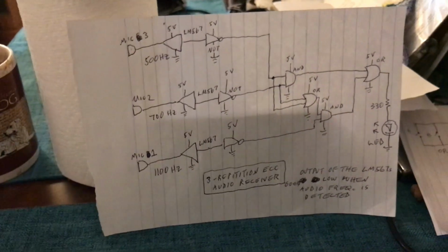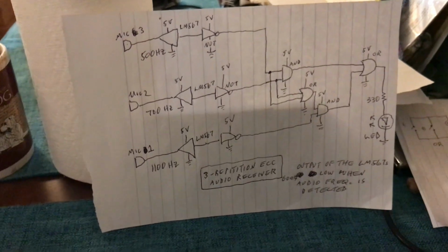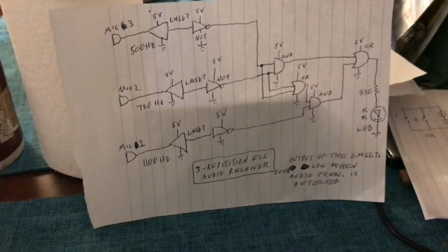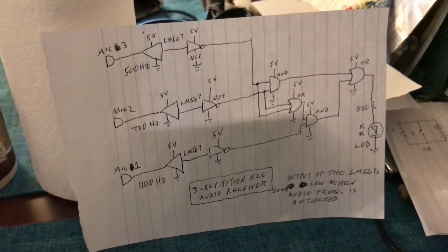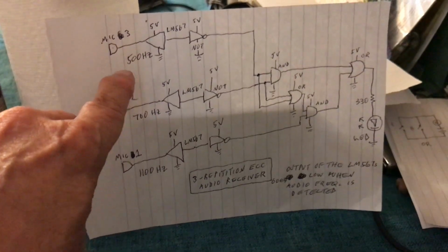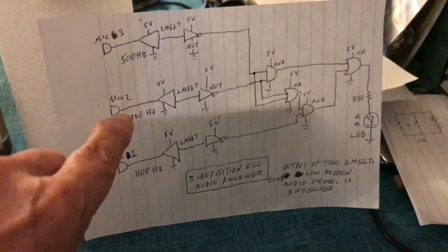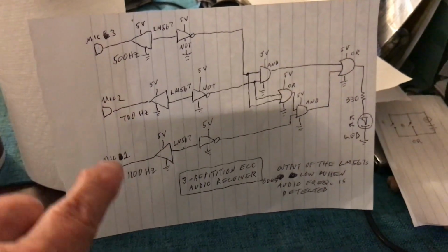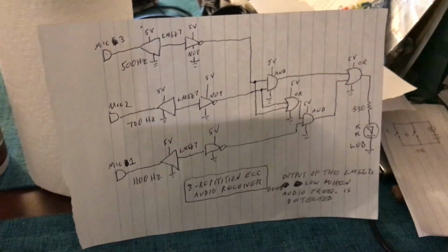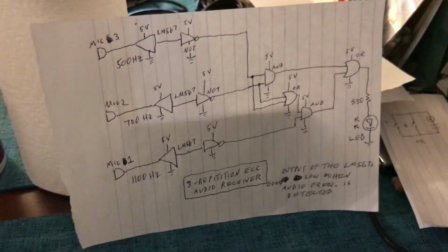And the same thing here for a 700 hertz and for an 1100 hertz. I don't know, these tones may be too close together. They certainly should not be multiples of each other, because anything, say, that produces a 500 hertz tone is also going to produce all multiples of that, like 1000 hertz and 1500 hertz, so we wouldn't want these to be set to detect those harmonics, and so on. These are not harmonically related, so if that's all that's needed, then this should be fine.